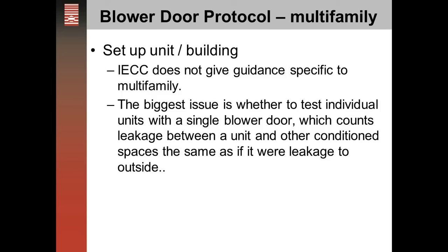In this section, we'll talk about blower door testing in the IECC. The IECC codes really don't give any specific guidance to multifamily other than how you set up a building for a single-family test. The biggest issue that you'll face is whether to test individual units with a blower door, or are you going to test it all as one space.